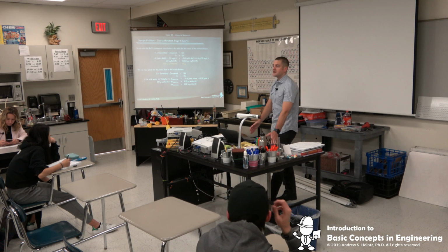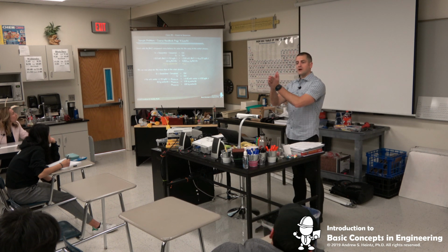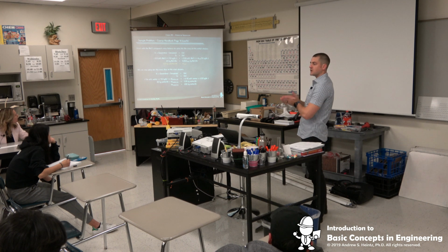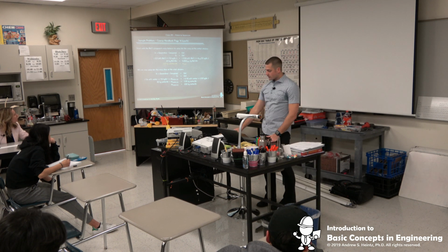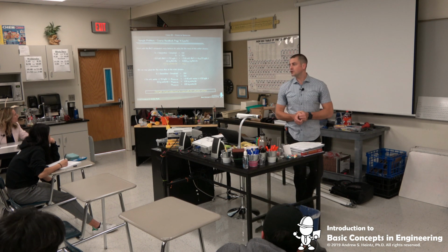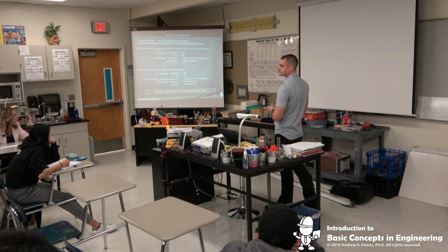200, right? So what we did is we used the component balance to solve for one of our variables, and then we plugged that back into our other equation to solve for our total. So our overall answer is we have to mix 200 kilograms per hour of pure water with our salt process in order to not kill the fish.